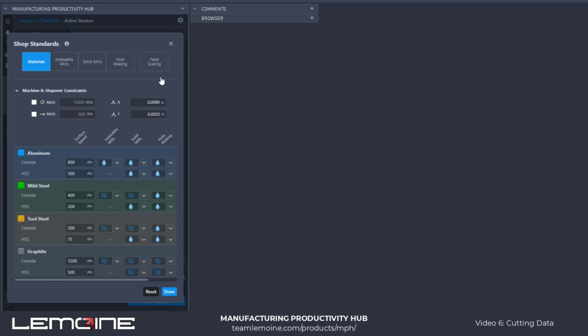where you've got 4 common materials. You're just going to decide what's going to be the surface speed that I want to apply to these cutters, what's going to be the default coolant settings for the various materials, right? And of course the various cutting materials as well, right? Tool materials. Does your tool or machine have a maximum feed rate? So you never want to go above your maximum feed rate, or RPM, that is.